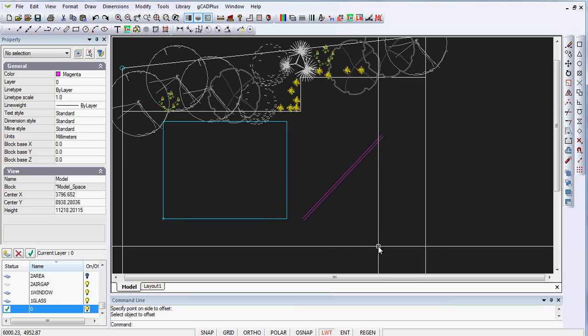So we're trying to use this mixture of different ways of locating entities just by mixing our coordinate systems, but all the time every one of these entities has a pair of Cartesian coordinates under it. You don't normally need to worry about them. It's much more common to be using relative coordinate systems and polar coordinate systems, as we've demonstrated here.